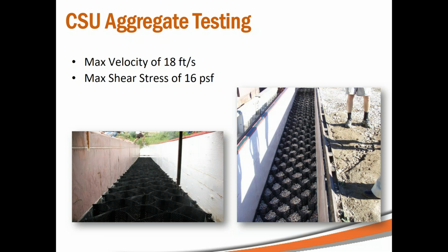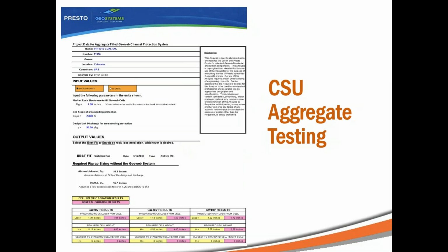Now, this isn't to say that aggregate channels aren't useful. They definitely have their place, especially in more arid environments or where stone is readily available, such as mine sites. If the flows can be withstood by either infill type, it becomes a question of aesthetics in the end.